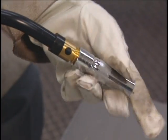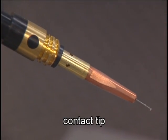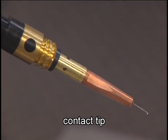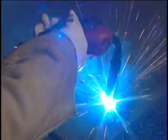The purpose of the contact tip at the end of the torch is to feed the electric energy from the power supply to the welding wire by contacting the wire to the inside surface of the torch tip. Then an arc is generated between the end of the wire and the base metal. This creates the molten puddle which joins them together.